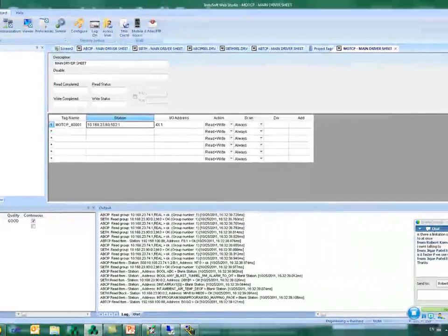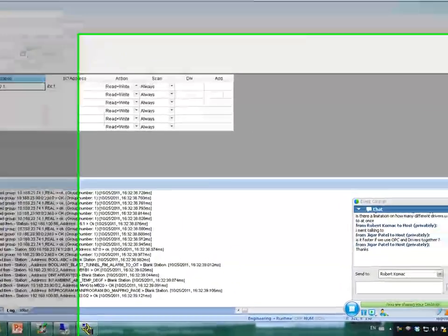So if you have an InTouch application running on one PC and you install what we call our InTouch gateway on that PC, we can talk to all InTouch tags through Ethernet. Okay, so we can send data right to these tags, read from these tags. Talking to the Suite Link specifically, no, but yeah, we can exchange data with InTouch.